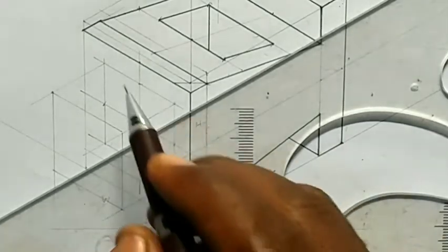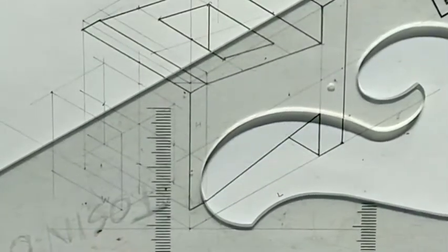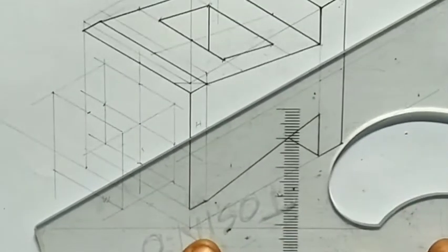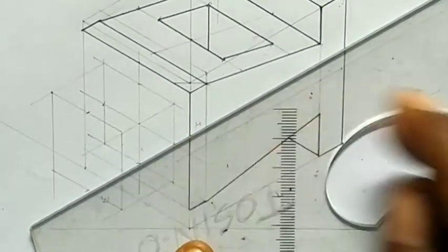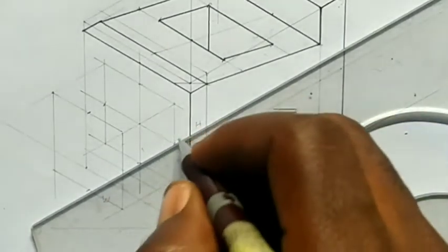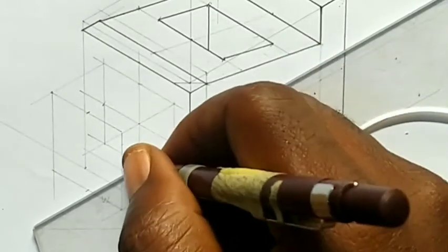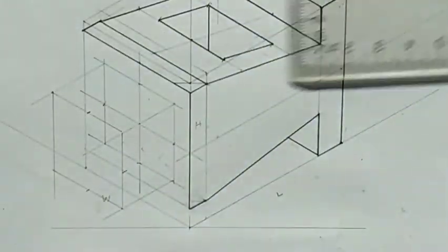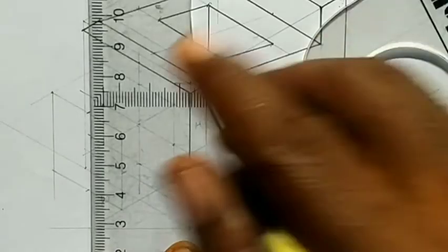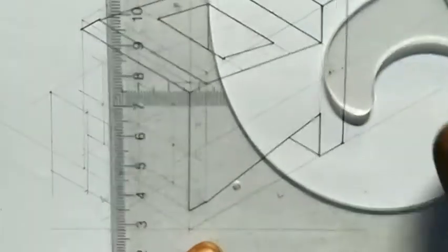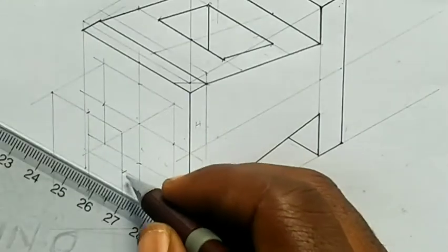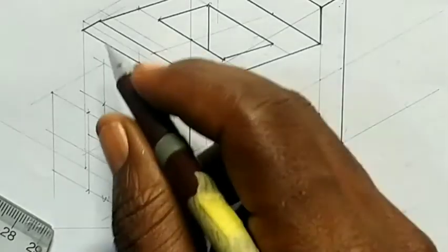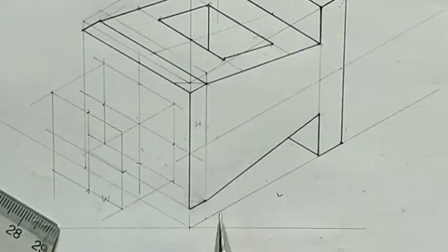Now look at the center of this one here. I'll use my t-square and my set square, and I will extend it to the other part here to get the center. I'll take this one too to get the center. All good. This one also to get this point. So I'll just join them together. So this vertical and this horizontal. So you notice it, I've divided it into 4.